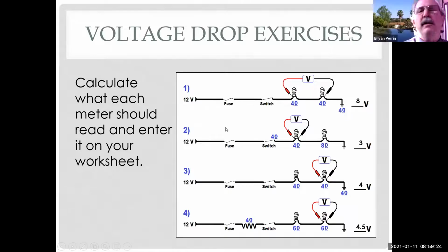Thank you. You bet. So the rule is divide voltage first by ohms, right? Because I did it the opposite, and that's why I got the answer wrong. Yeah. If I want to figure out the voltage drop across multiple resistors in a series circuit, I have to first figure out the current flow of the circuit. So you figure current first, then use that current to go back with each resistor to figure out the amount of voltage each resistor uses. Thank you, Mr. Ryan. You bet.